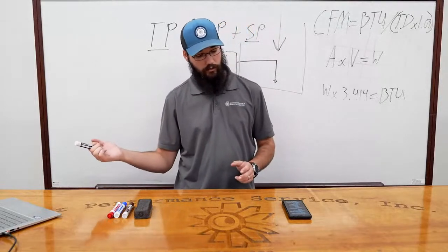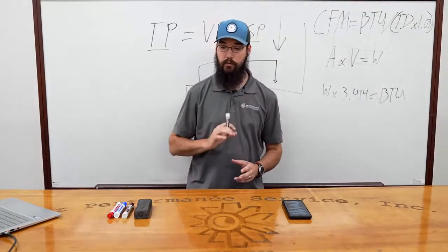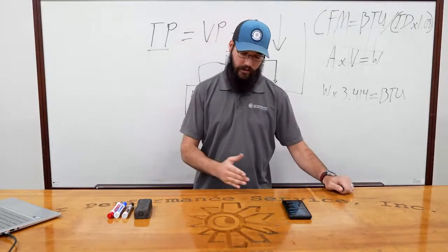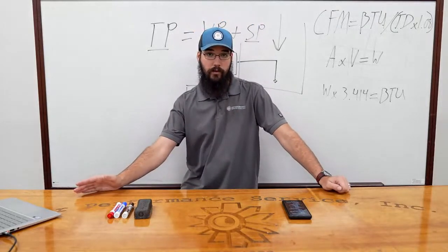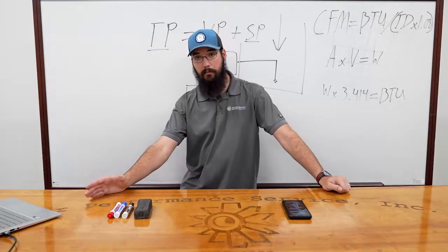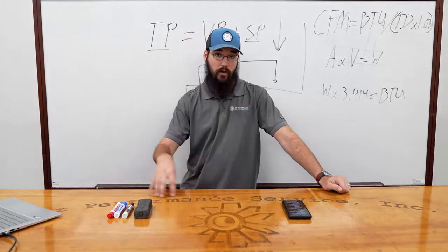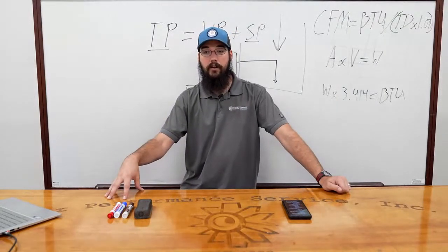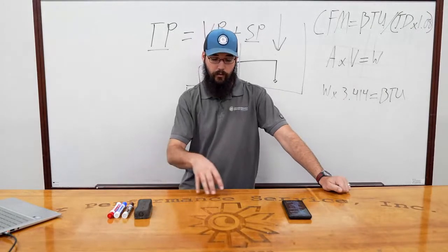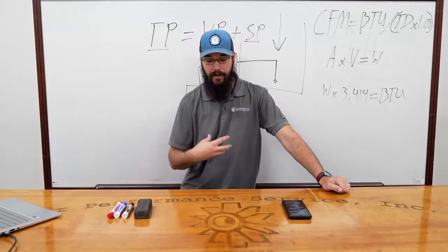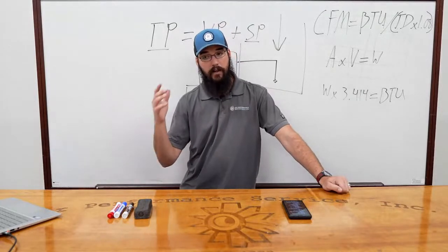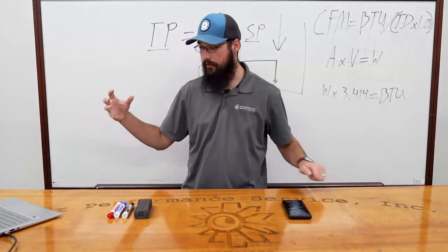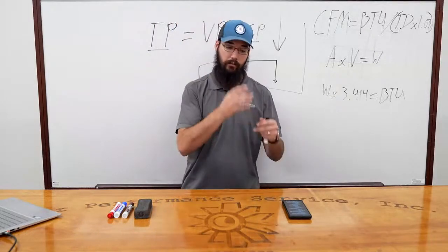Same thing if you go the other way, where we're moving too much air. We're flying it through that coil. That's going to cause its own issues. For example, condensation wicking off the coil can be a big issue for you, especially on a draw-through coil. RTUs, and basically most of what we work on, are draw-through evaporators. So you could wick. If you open a panel and the whole inside of it is wet, it may not be a leak in the pan. You may just be sucking that condensate straight off of the coil, and it's not making it into the pan when it goes to drip down.